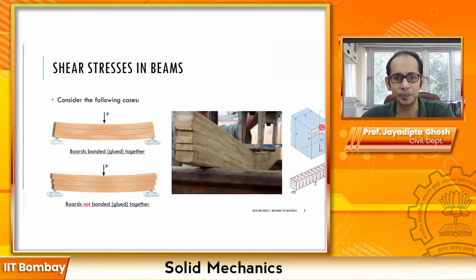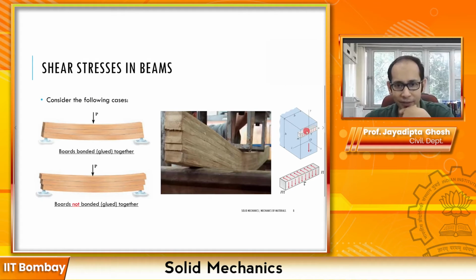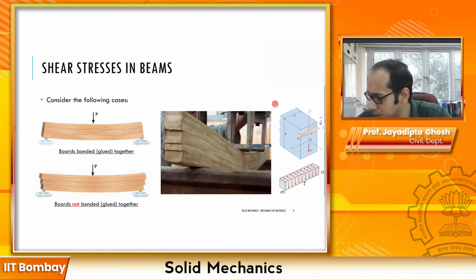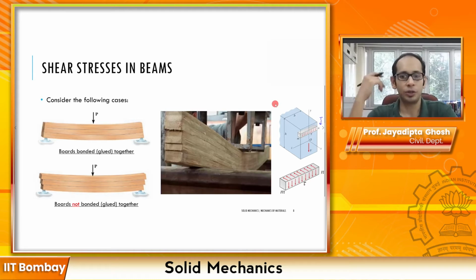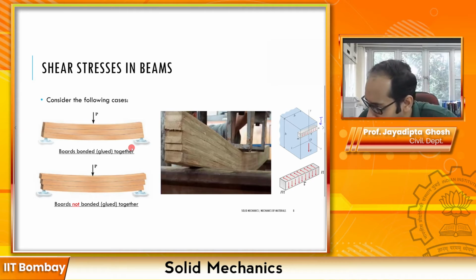It tells you that although you have this stress in the transverse direction, which is in this particular direction, which we call the transverse direction over here, right? You also develop tau because of complementarity. Remember what we discussed in complementarity, that if we take a small element and you have tau on one of the faces, you are going to have tau across all four faces. Because of this force, you have this tau over here, and as a consequence of complementarity, you will have a tau here. You will have a tau on the back side face and the bottom face as well. This is not shown over here. So this tau is the shear force, which is acting at all these interfaces, which is resisted by this glue which you are seeing over here.